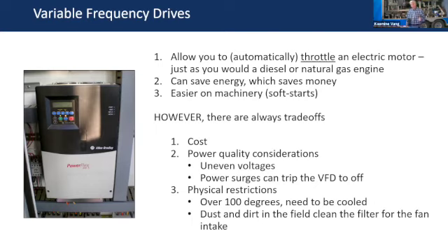Well, the same thing at that time, this is 20 some years ago now, VFDs really weren't coming into play very much in agriculture yet. Now they're becoming very frequent when you have those kinds of conditions where you have different size blocks, different emission devices, different flows and pressures, basically. We don't need full speed all the time. Slow the pump down, saves a lot of electricity. So that's what it does. It also can be easy on the machinery. Soft starts, we'll demonstrate that.